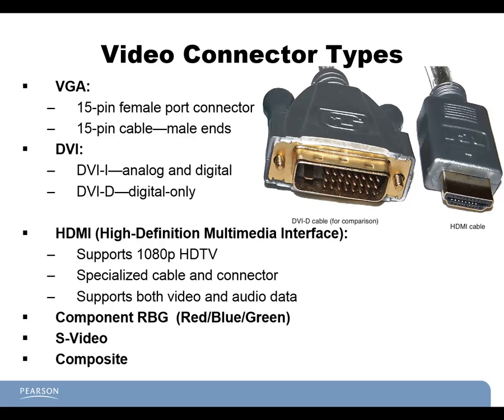DVI-I handles analog and digital connections. Most modern video cards are going to be DVI-I, and the reason for that is that you can put a little adapter on the back of your video card that runs from DVI into VGA so that you can plug a VGA monitor in. DVI-D, on the other hand, is digital only.